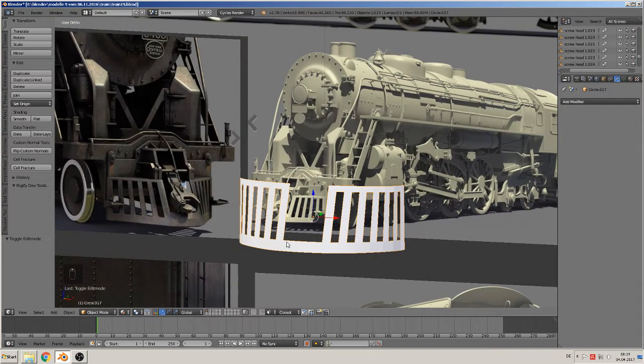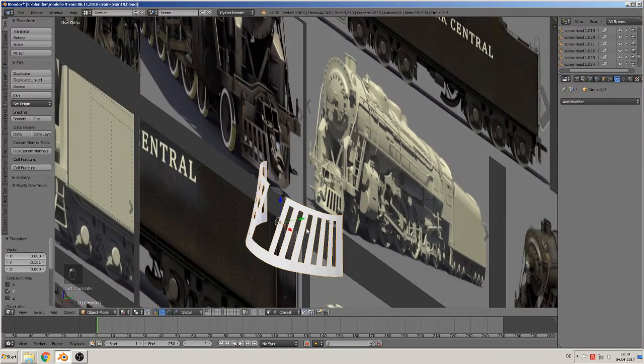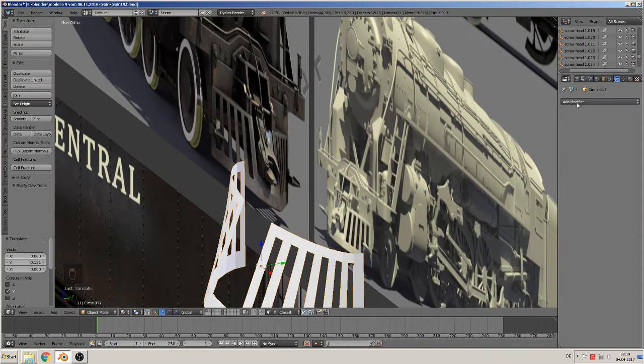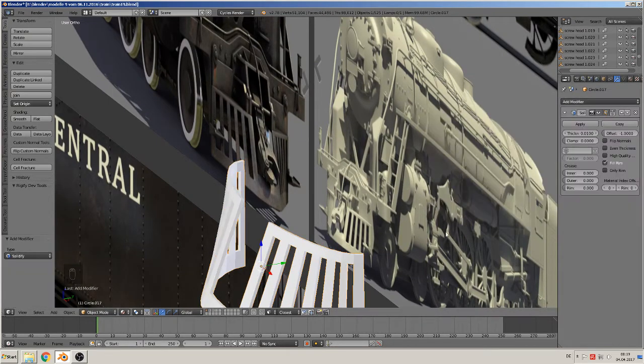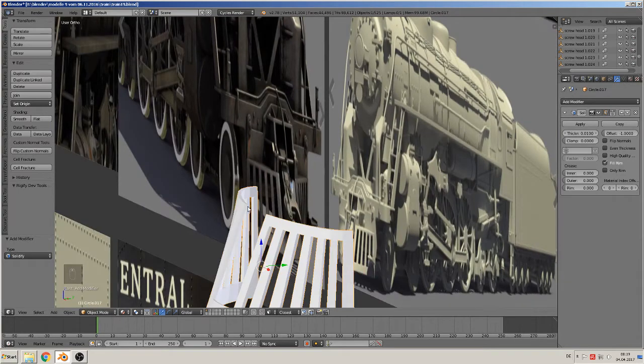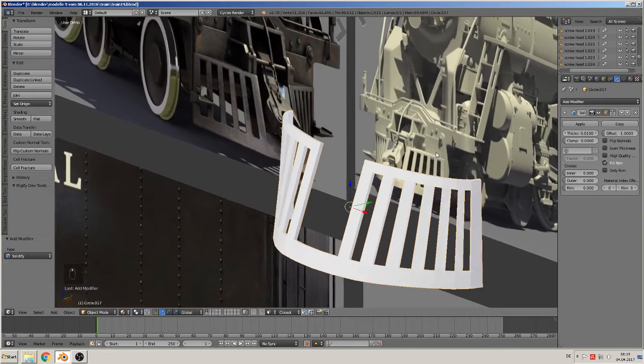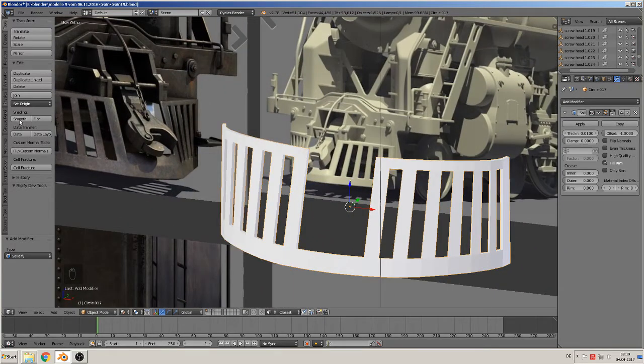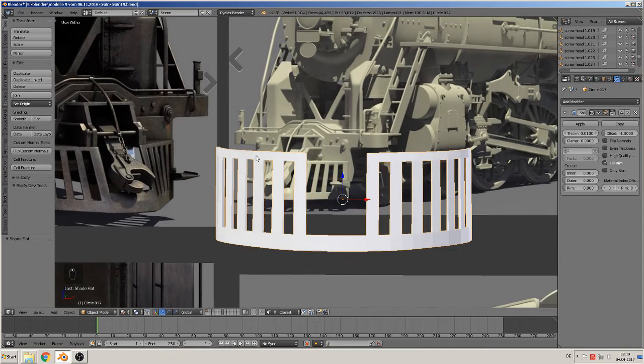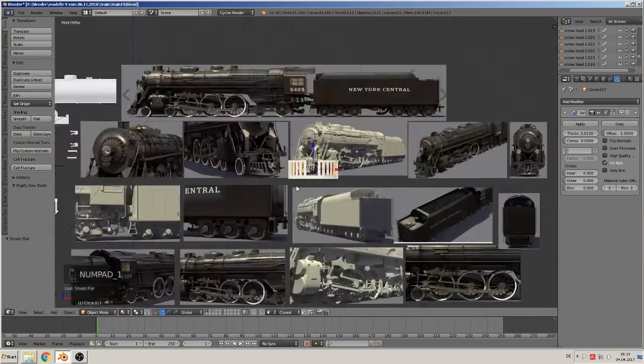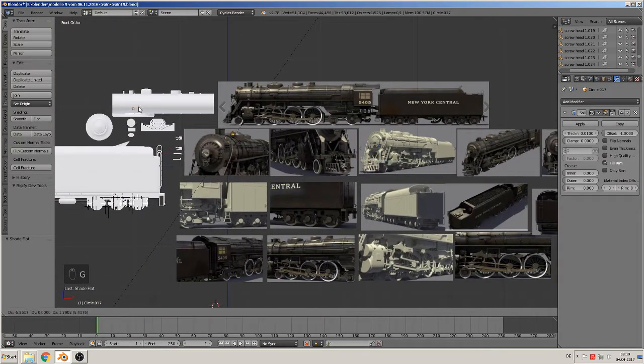Now you can handle that for controlling all, but it has no thickness, so we need here a solidify, and you see now that it's thicker, and you can tweak that here. Okay, then we can take a smooth on it or not, like you would. I will take none because it's a sharp thing, so we can bring that back to the side. Good. File, save.